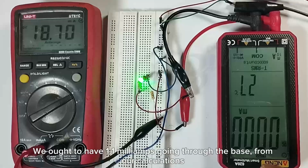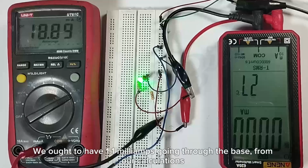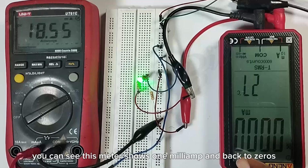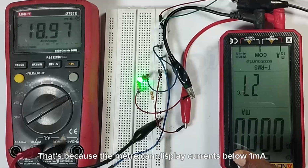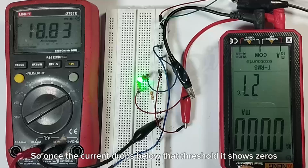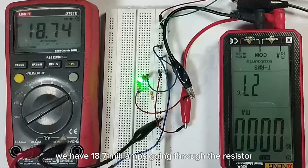We ought to have 1.1 milliamps going through the base from our calculations. You can see this meter shows 1 milliamp and goes back to zeros. That's because the meter can only display currents of 1 milliampere and above, so once the current drops below the threshold, it shows zeros. While here, we have 18.7 milliamps going through the resistor.